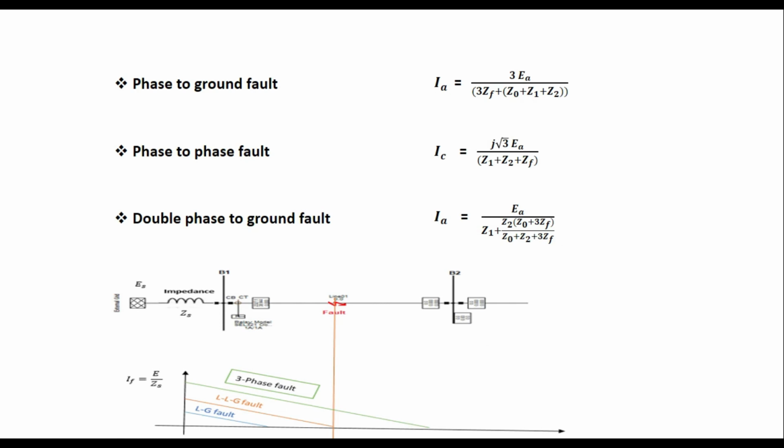If we consider this diagram, we see that the fault current decreases as we move further from the source, as we already discussed. But the reach for these 3 types of faults is different, because at the same location the current due to a fault is not the same.